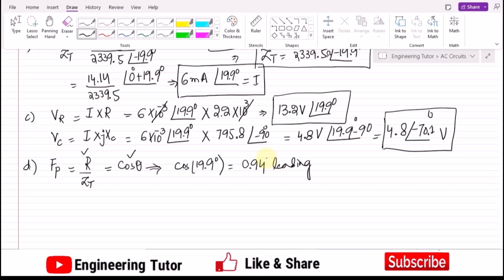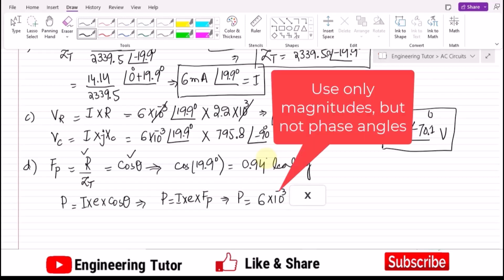Okay, so now I have to find the power. The power here is I multiplied by E, multiplied by the power factor, which is cos of theta. So I multiplied by E multiplied by power factor. Now putting their values, I have 6 milliamps, 10⁻³, with the angle of 19.9 degrees, and the value of the voltage was how much?